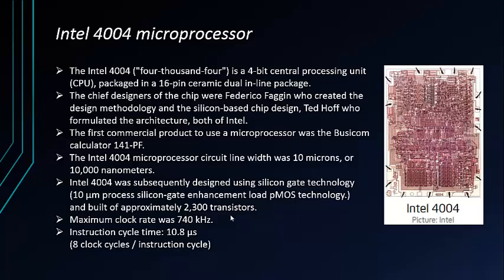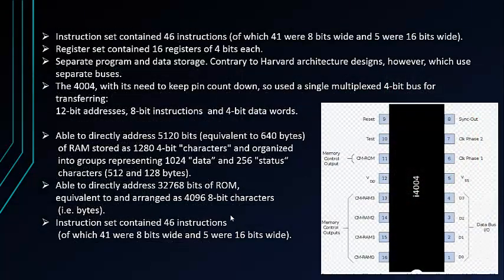The Intel 4004 had a program memory size of 4 kilobytes. All conditional instructions work within the currently selected ROM. It has 16 4-bit input ports and 16 4-bit output ports. The 4004 instruction set consists of 46 instructions, while the instruction length can be 1 or 2 bytes.